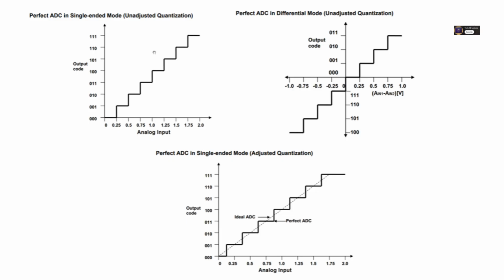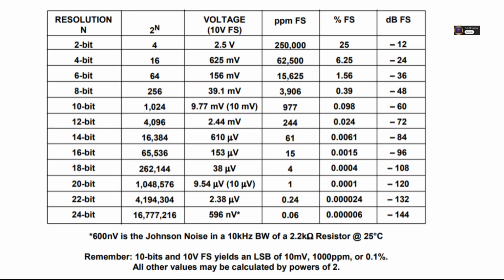And this is where bits come in, right? Like when we hear about an 8-bit or a 16-bit ADC. Exactly. Resolution is expressed in bits, commonly 8, 10, 12, 16, or even 24 or 32 bits for really high-precision scientific or audio applications. An n-bit ADC divides the total input voltage range into 2^n discrete steps or levels. So a 10-bit ADC? Right. A 10-bit ADC quantizes the signal into 2^10, which is 1024 unique levels.